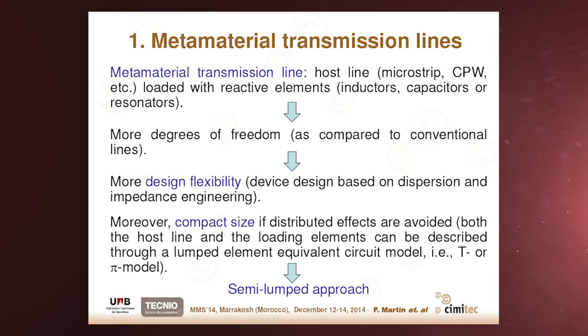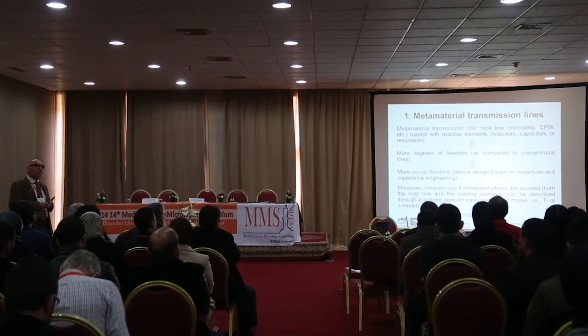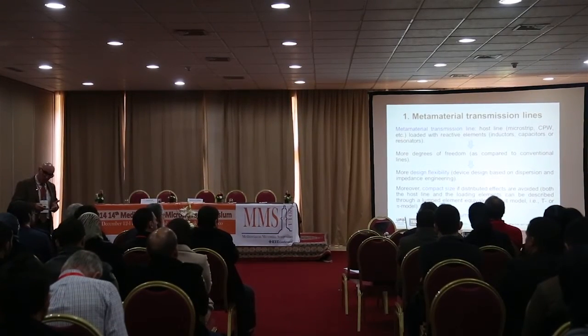Thanks to the presence of these reactive elements in the line, we have more degrees of freedom for design as compared to conventional lines. So it means that we have more design flexibility, so that we can make device design on the basis of dispersion and impedance engineering. This is the key aspect. Moreover, we can achieve compact size if distributed effects are avoided, so that these lines can be described typically by lumped element circuit models, so that we are in the domain of the semi-lumped planar approach.